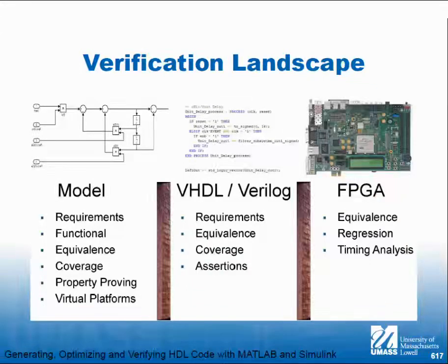When we put it into the FPGA, it's another equivalence step, but we can do regression, right, which is in this case similar to it, but we make sure that the tests that ran on the HDL model also run on the FPGA. And when we do the FPGA, be careful the way this is written. When we do the FPGA implementation, we're going to do timing analysis. So timing analysis isn't taking a code, putting it in the FPGA, running at full speed, and seeing if it works, maybe hitting it with the freeze spray or something. No, it's the implementation process that runs static timing analysis. So that's the timing analysis that we're talking about here.